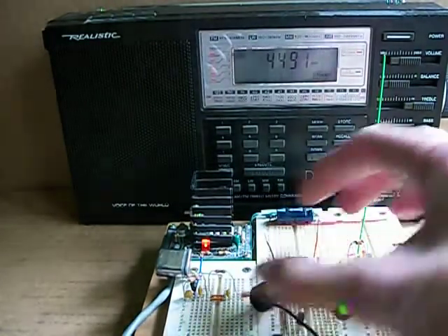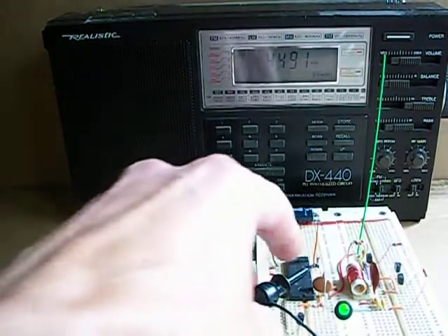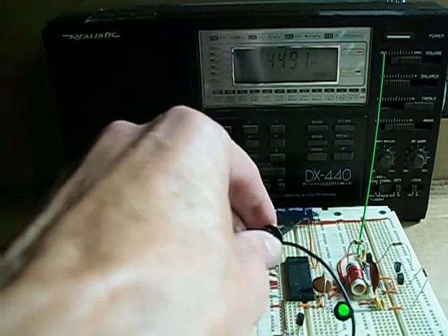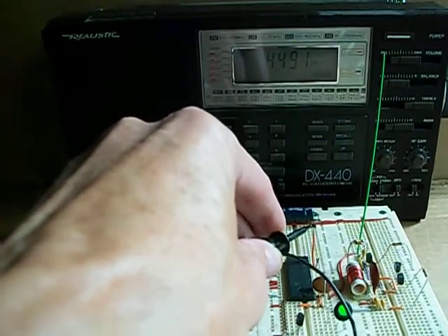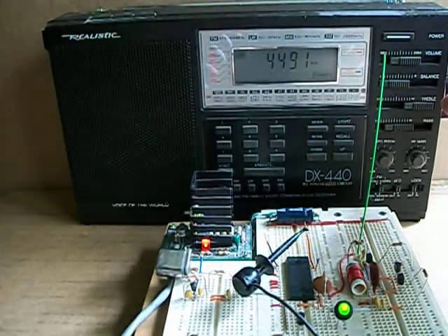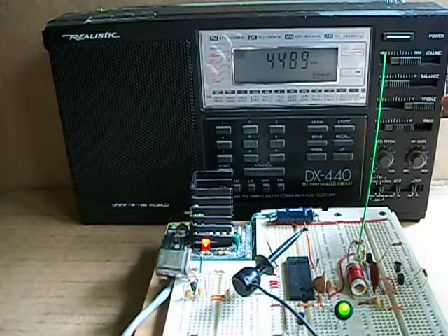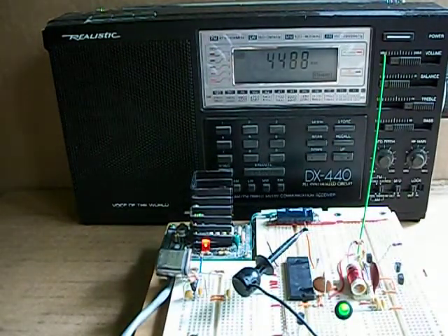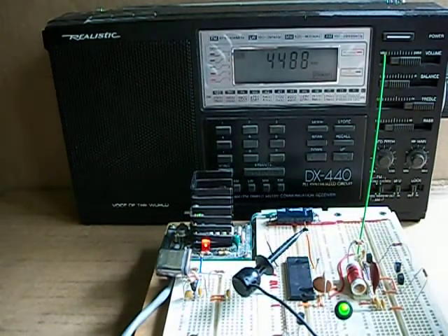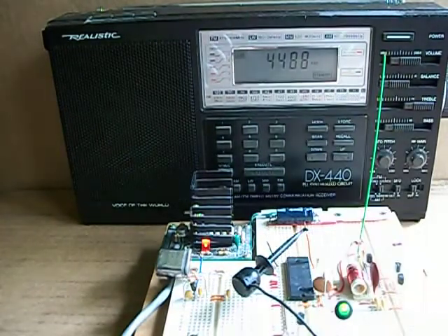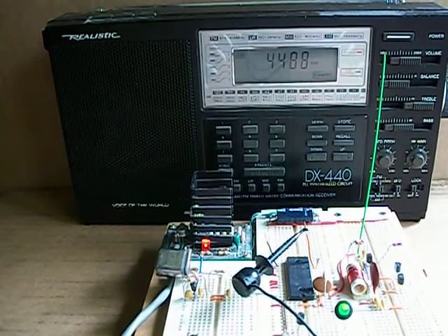So it's a little higher than the calculated value. The next bit down should be 1800 hertz different from that. And this is the reason I didn't do the 900 hertz one. So this one should be around 4.487. It's 4.488. It's not too bad. It's pretty close. But it's about 1800 hertz lower than the first one.